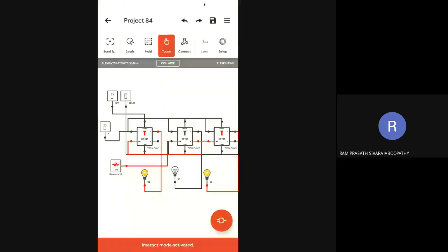See, whichever output I give as the clock matters. It is positive edge trigger, so the complemented output should be given as a clock to the successive flip flop for counting up. If it is negative edge trigger, the normal output must be given as a clock to the successive flip flops. That's all.